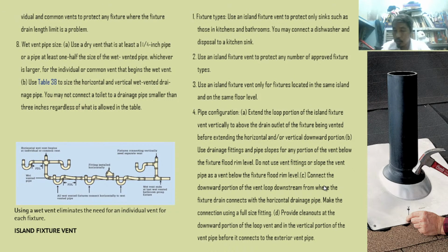So the plan for the water closet is 4 inches, but the minimum you can use is 3 inches. Therefore, do not follow the table if the table indicated smaller than 3 inches. That is what we mean by this.